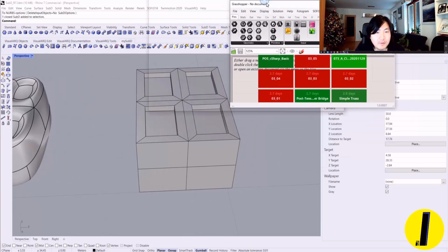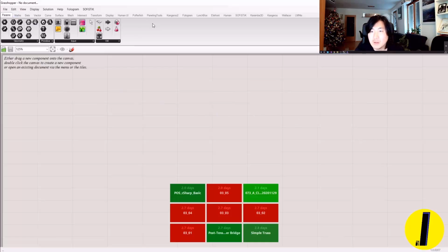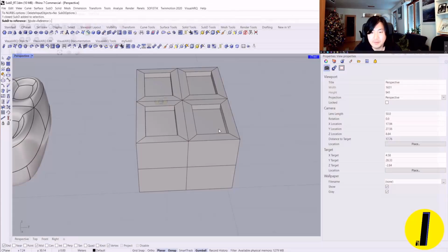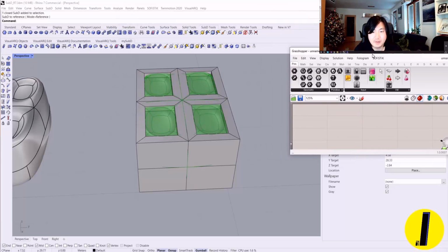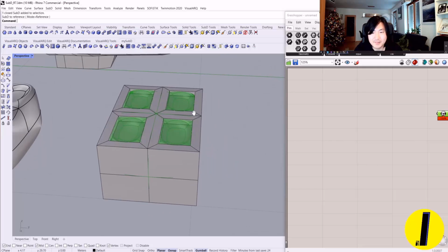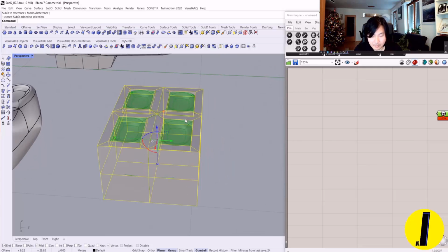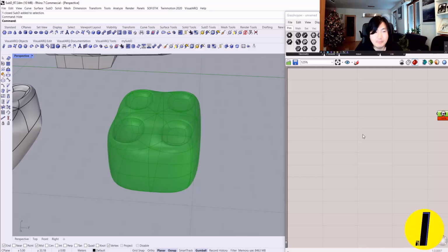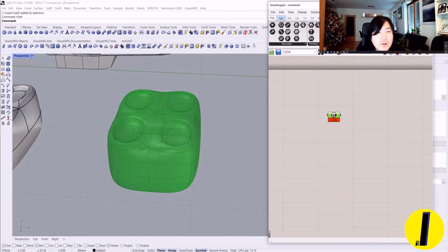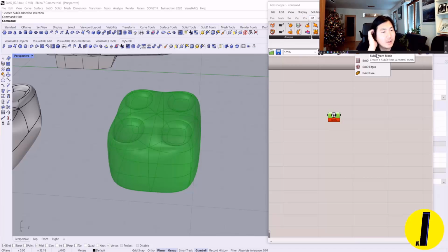But in Grasshopper, if I look in SubD, let me type SubD, and we can reference SubD geometry from Rhino. I reference one of these. And as soon as I reference it, it shows this smooth geometry already. Let me hide this. But on the SubD tab, when you go to surface and you go SubD, we can do the mesh from SubD option.